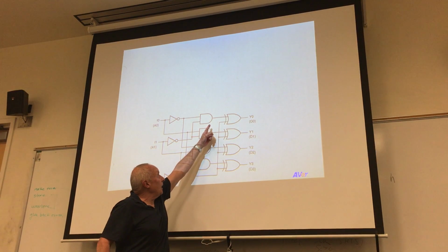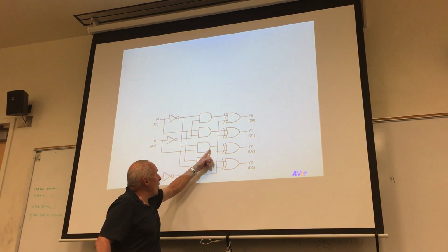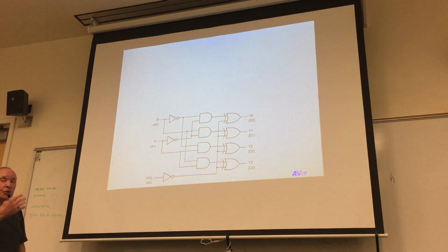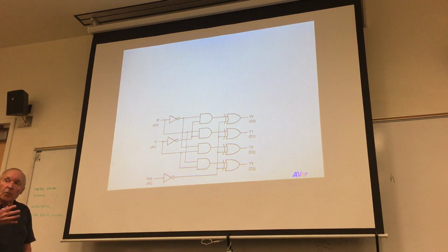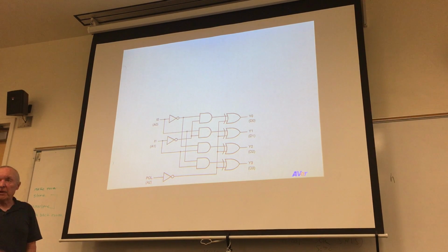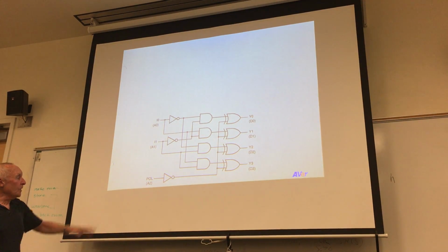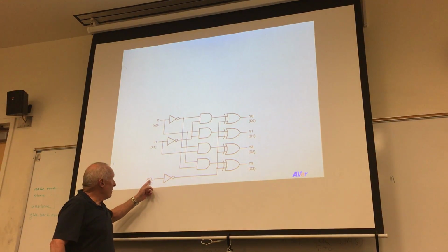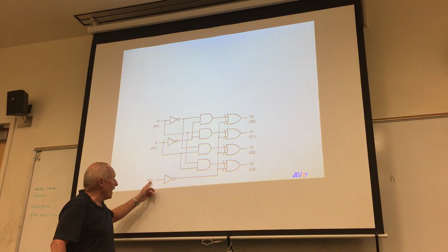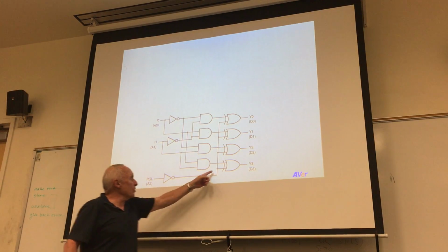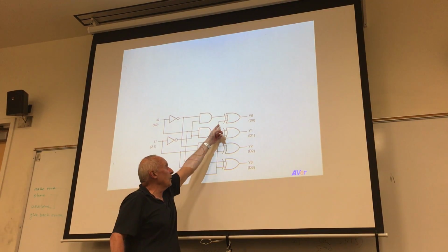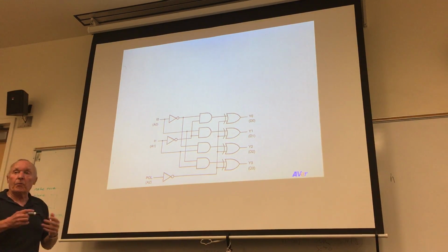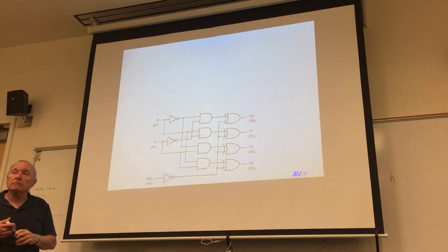If I took the Y's off of the output of the AND gates, then the asserted output would be a logic 1, and the rest would be logic 0s. This allows me to redefine that if I want to. By making this polarity a logic 1, that puts a 0 on all of these, and so the asserted output would be active high.